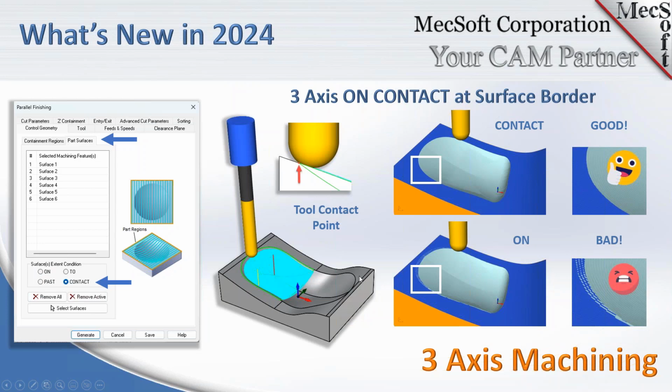Now, this is one that goes to my heart specifically, because I've always felt that we needed better contact conditions for mold makers, specifically around the parting lines. And in version 23, the default condition was the on condition, meaning that I'm going to show this a little bit better in the part file demo, but in the on condition, the tool axis in the tip of the tool, when it aligned itself with the perimeter curve that you're machining, it would stop.